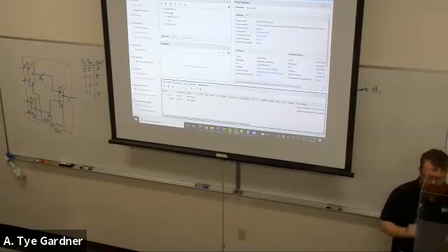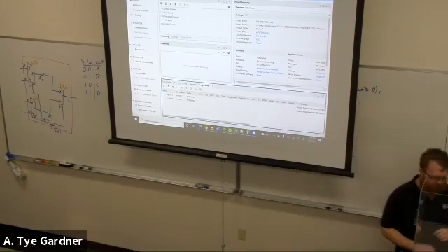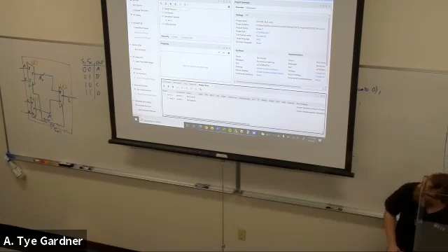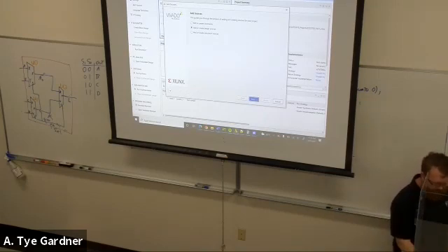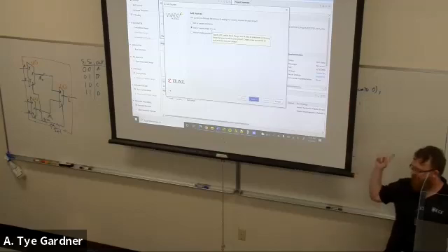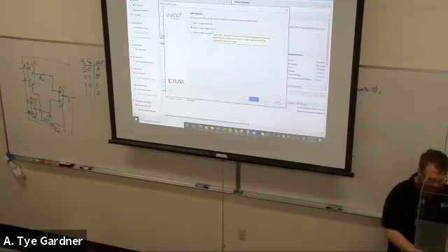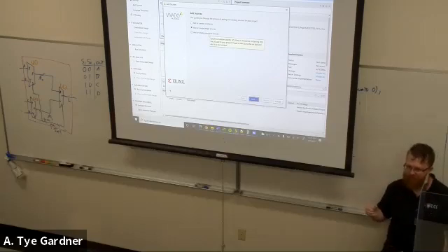All right, this is your main project type window. What you can do here is things like add sources. You see where my mouse is here? See that plus button? If I click that one, this is my add sources. Design sources is your main thing. The MUX, the MUX4, all of that is going to be a design source. Constraints files we'll get into later, and simulation is kind of obvious. It's a file to tell it how to simulate.